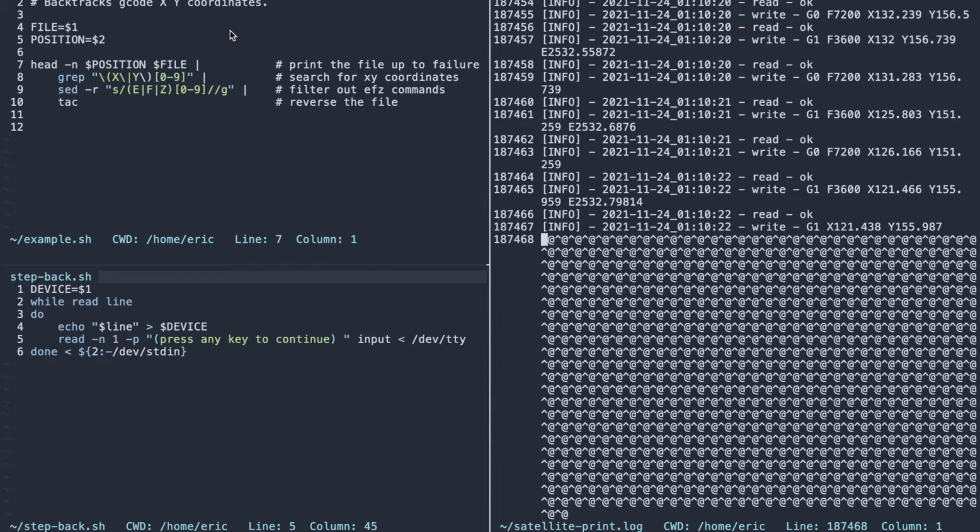Now, what I want here is the 3D printer to hover over the print that is still stationary on the bed, and I don't want that Z axis to move. I don't want it to dispense any filament, and I don't want it to heat up or do anything like that. I just want the X and Y axis to move so I can go backwards in the code one line at a time and see the position.